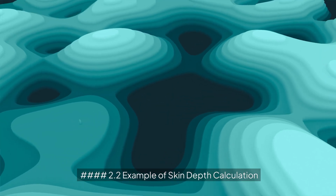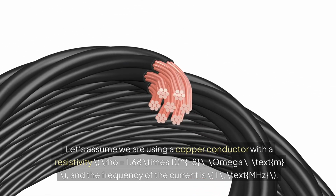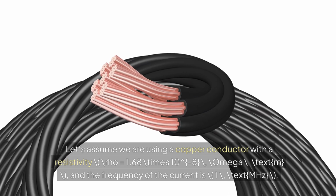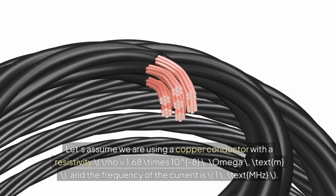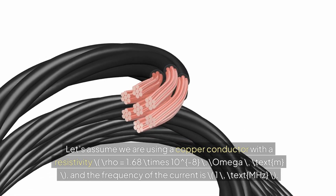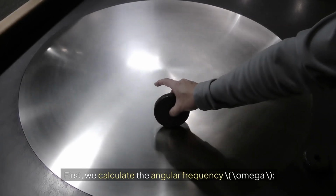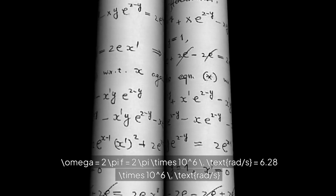Number 2.2. Example of skin depth calculation. Let's assume we are using a copper conductor with a resistivity ρ = 1.68 × 10^-8 Ω·m, and the frequency of the current is 1 megahertz. First, we calculate the angular frequency ω: ω = 2πf = 2π × 10^6 rad/s = 6.28 × 10^6 rad/s.